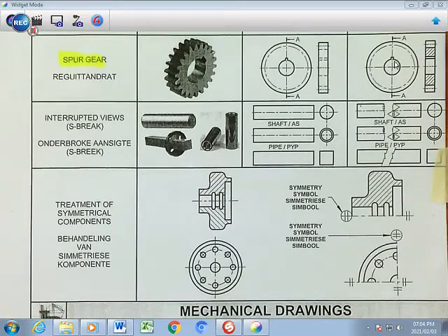The shaft goes through there, and you have a keyway there that locks the shaft to the gear, the spur gear. And there it has been cut, the full section, which we spoke about now. There's hatching, cross hatching, there, because there's contact with the metal. Here in between the teeth, it's not cut, in between the teeth, not cut, and the shaft opening basically doesn't allow for hatching there as well.